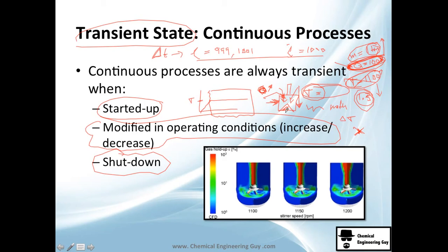So what you need here, guys, is to do the same thing we've done before, but for a shutdown. So probably you're going to decrease your fuel consumption. I don't know, maybe some kilograms per day. You're going probably to reduce temperature in a very slow way. Maybe, I don't know, 10 degrees per hour. It would take a lot of time, yes, of course, but you need to let the material or the oven walls rest, because if not, they're going to contract and break and generate cracks everywhere.